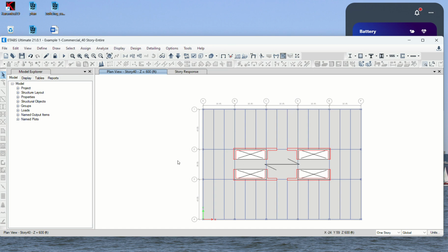The wind load is based upon building geometry, but you could see that your core layout, right, and the associated stiffness is the other way around. Our core is laid out mostly in the X direction, so this concrete core wall's overall stiffness is much greater in the X direction than in the Y direction. I think you studied this in homework 1, but now we're going to make it 3D.